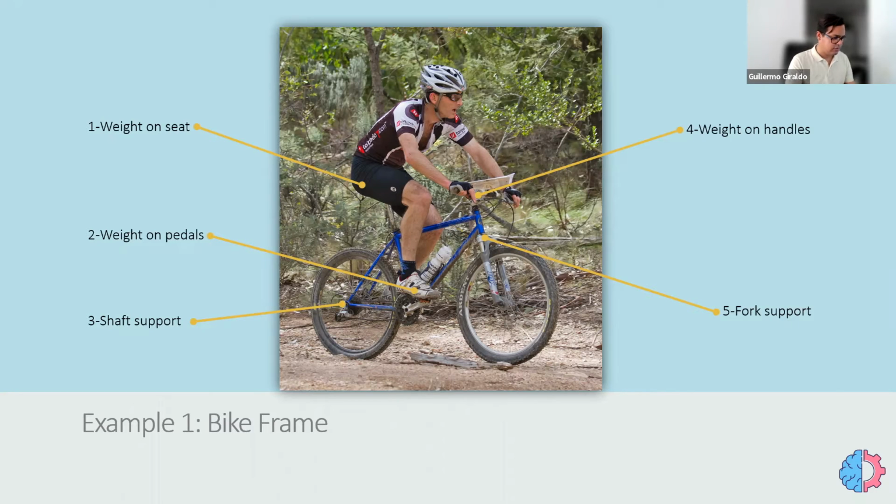And they say, hey, you are an FEA analyst, I need some FEA simulations to help us improve our design before we start building our first test models or our first prototypes. So let's think about it in a systematic way: what we need to analyze, what the environment is, and what the interactions are between our system or target component and its environment.